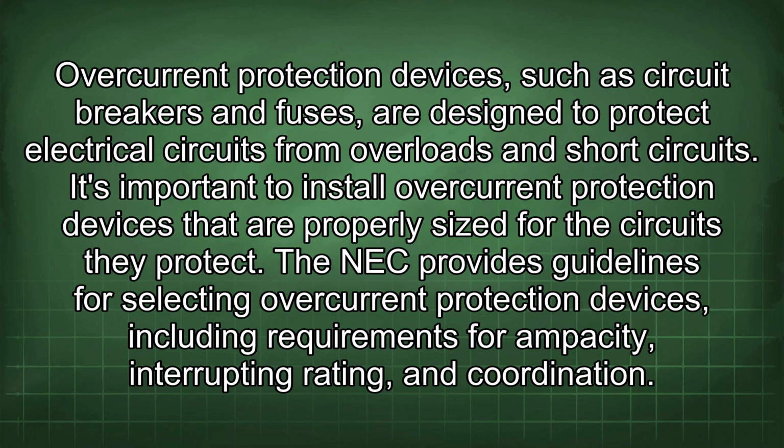Overcurrent protection devices, such as circuit breakers and fuses, are designed to protect electrical circuits from overloads and short circuits. It's important to install overcurrent protection devices that are properly sized for the circuits they protect. The NEC provides guidelines for selecting overcurrent protection devices, including requirements for ampacity, interrupting rating, and coordination.